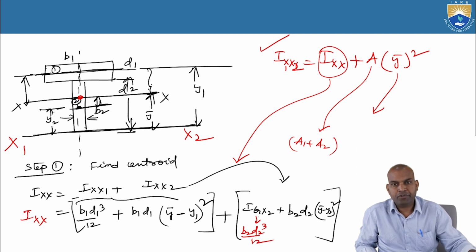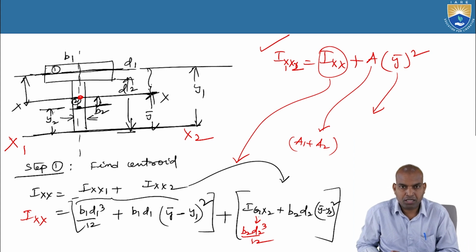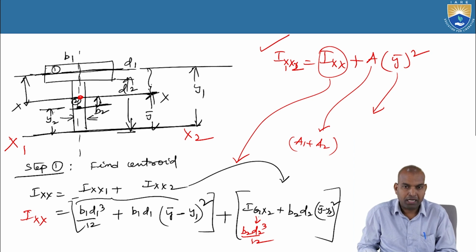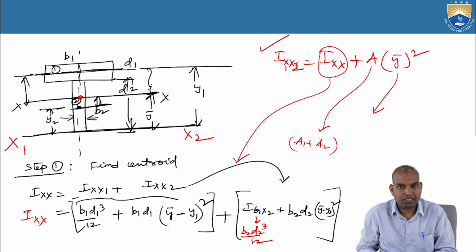In this session, we have revised the previous sessions, used the parallel axis theorem, and solved problems by using it. We calculated the moment of inertia of the I section, which has two lines of symmetry, and the T section, which has one line of symmetry.